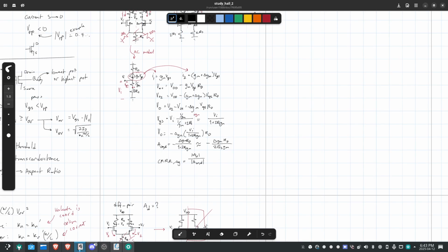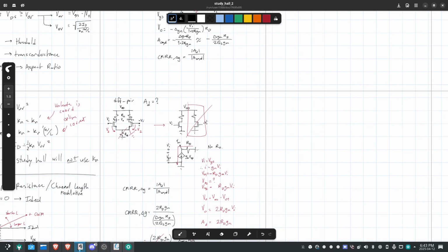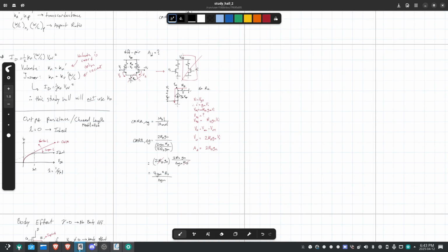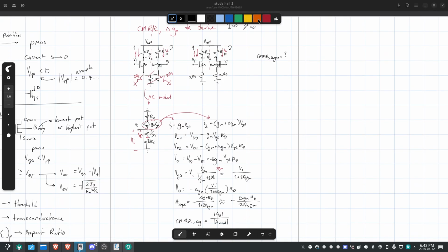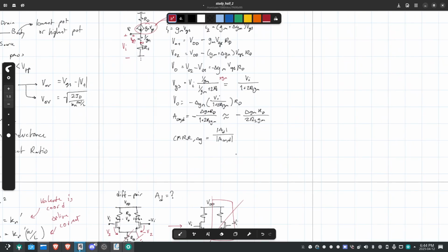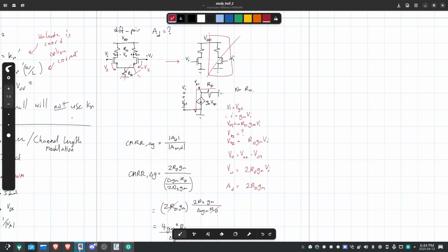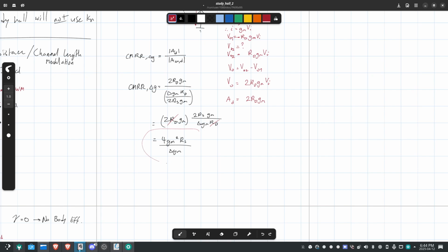I hope I explained this question decently enough. Does anyone have any confusion? Hopefully that cleared up something for you guys. So you understand how you work common mode. You find the common mode amplification, and then you find the regular amplification in differential mode, and then you just divide them, right? The regular amplification divided by the common mode amplification, and we call that the rejection ratio.